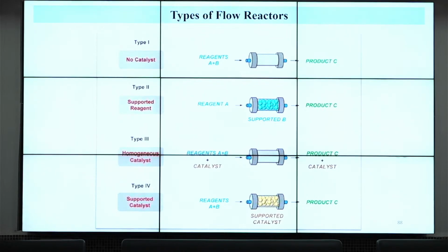You put the substrate on one side and keep the hydrogen on it. Automatically the hydrogenation reaction will be going on and it will be coming to the other side. You need not do anything, you only have to take a pump to make the flow of the reactions. Once the pump is there, it will be sucking the material from this side and pushing it to the other. If you see the reaction doesn't go to completion, you can channelize it again through that cartridge.